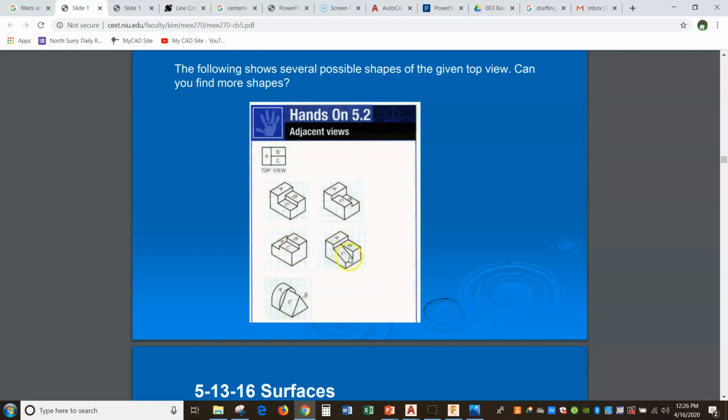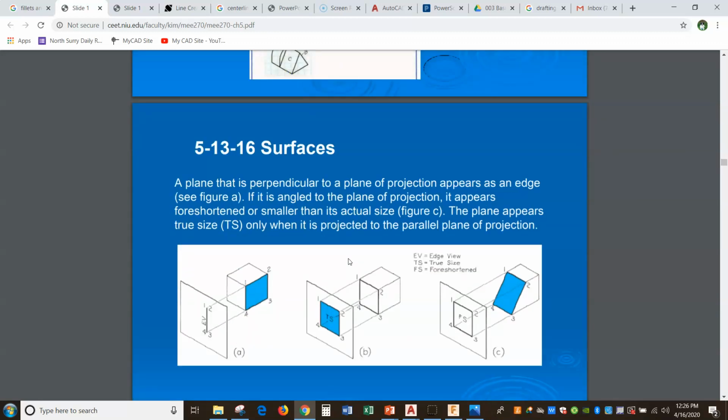Here we've got an inclined surface, it's on a slope, but we still see a rectangular shape and it just goes over to the right-hand side. So the 3 things we'll see in the top is that as well. And in the exact same thing here, we can have a fully rounded top, but if you look straight down on it, it would look like a rectangle. And in this triangle, we would see a rectangle on this side and a rectangle on this side. So this is the correct top view for all 5 of these. That's the reason why you have to draw more than 1 view. That way people can tell exactly what they're looking at. You've got to give enough information.